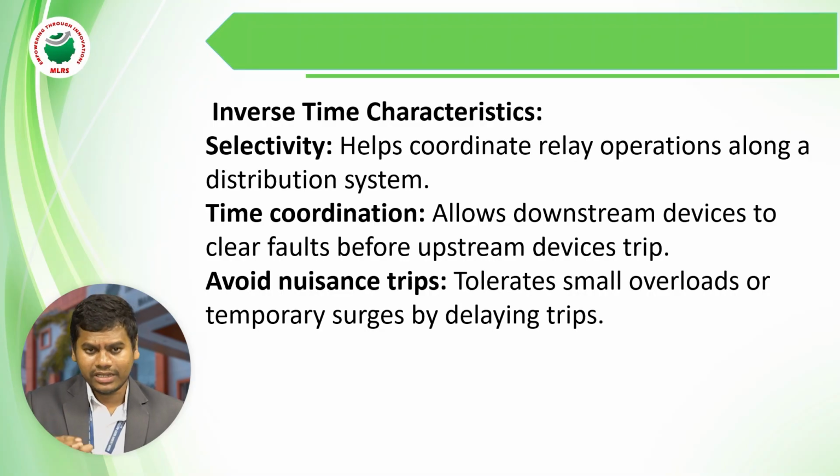Next, time coordination. Time coordination allows downstream devices to clear faults before upstream devices trip. What he is saying, time coordination is a very simple thing. What is that? It allows downstream devices to clear faults before upstream devices trip. So that is the time coordination.